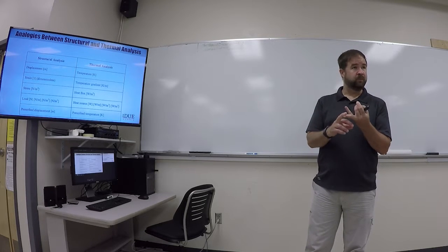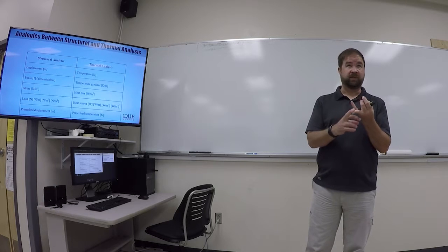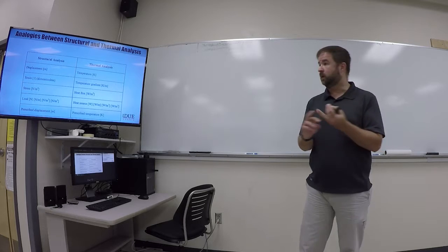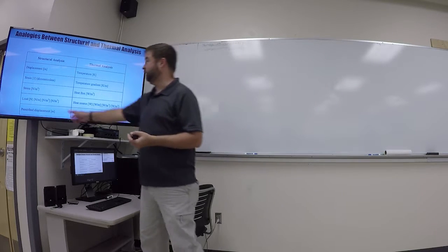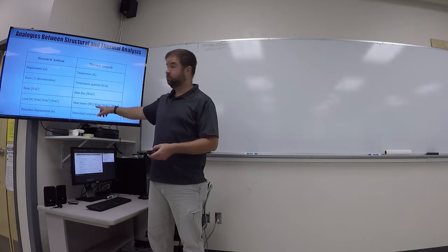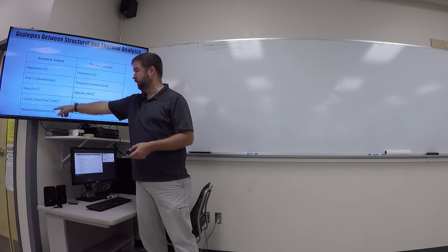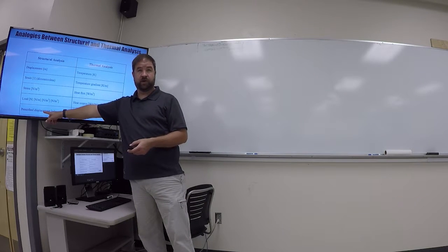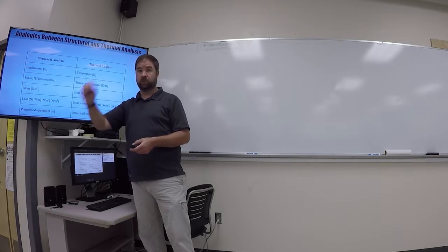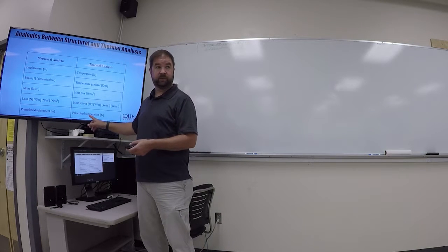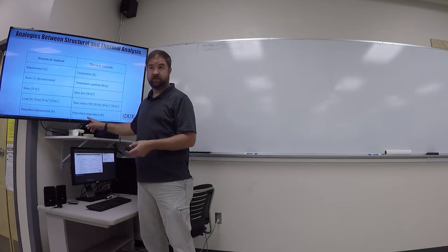So in the case here, constraints would be essentially places where loads are, right? And so depending on what my constraints are, I'm going to need some heat sources for my thermal analysis, or possibly, prescribed displacements could also be a constraint. For example, my prescribed displacement could be 0. If I've got a support where it doesn't displace, then it's 0. So I know the temperature at that point. That's my constraint in my thermal analysis.